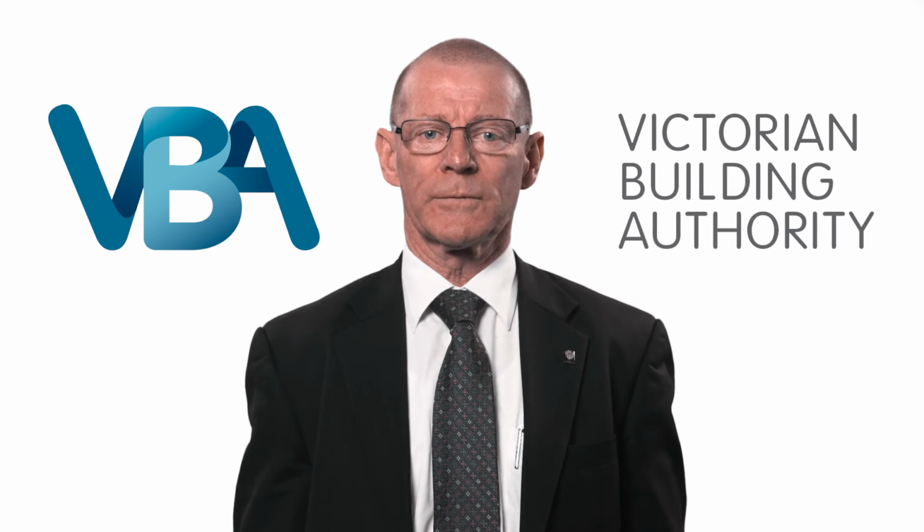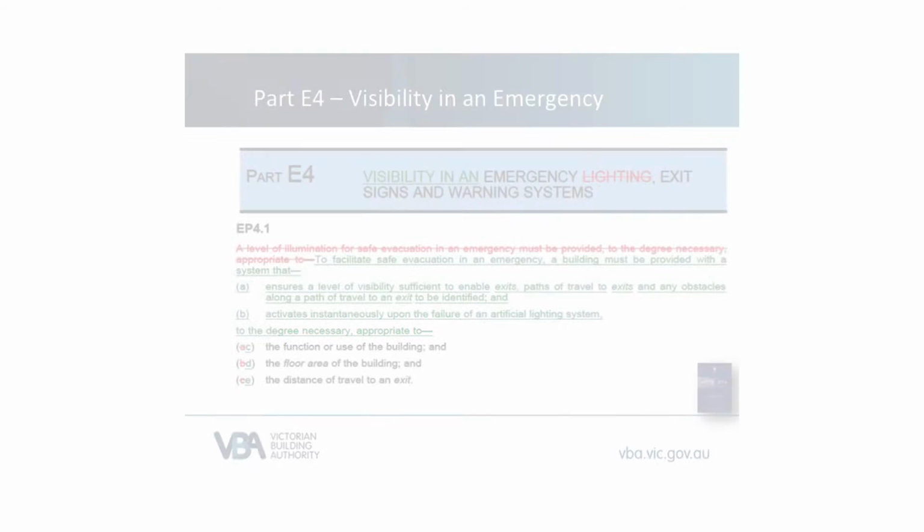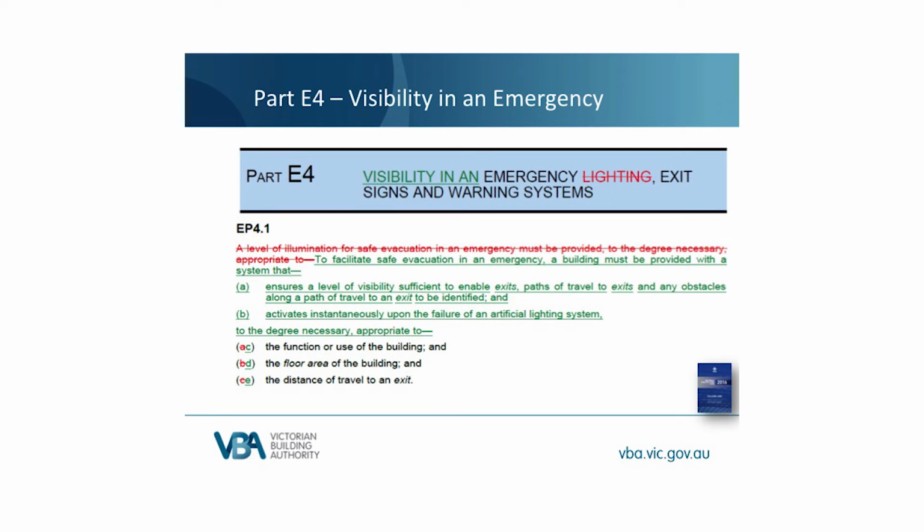The increased use of performance projects recognised that FV4.1 was potentially preventing innovation by limiting visibility in an emergency to that provided by the lighting only. So the ABCB changed lighting to visibility to enable other systems. As you can see, the title of Part E4 has also been changed accordingly.